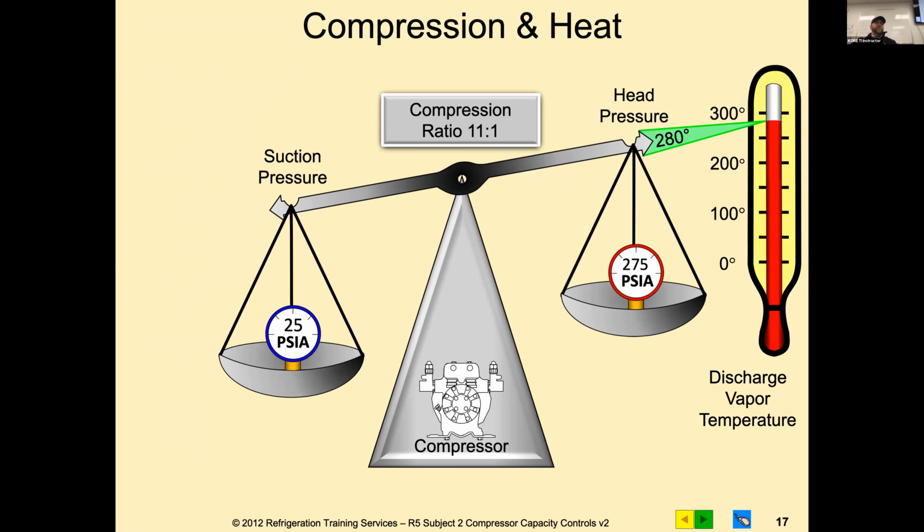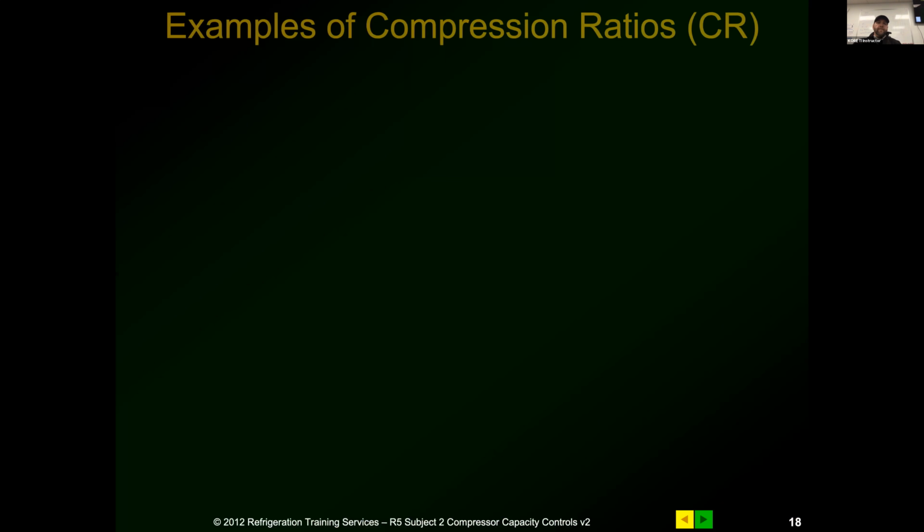So as you see that suction pressure drop and your head maintain, you see how it absorbs less heat, your discharge pressure continues to go up. Again, you're getting less volume per stroke is what it comes down to at the very baseline level. You're filling that cylinder, you're having to satisfy the volume in that cylinder, and the pressures have to equalize before that suction reed opens up and allows more cool gas to go into the cylinder at the compressor.